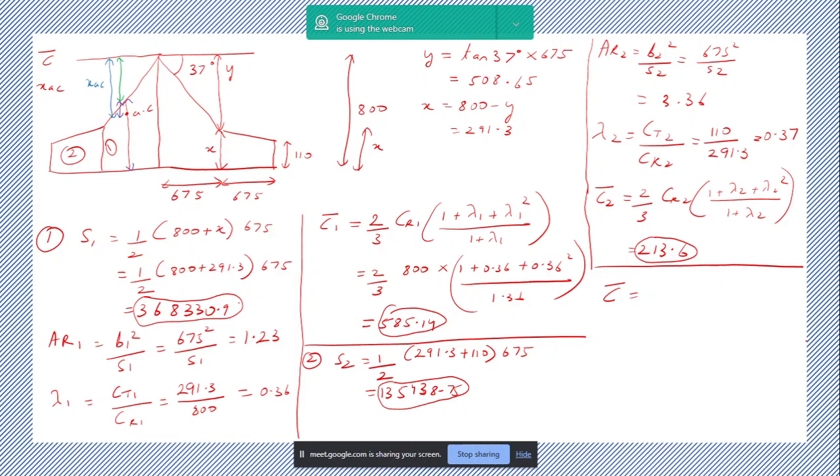It's very analogous to the center of mass. For the centroid, what properties do two-dimensional bodies have? We can't just do c bar 1 plus c bar 2 by 2, because this body can be any shape, right? So what defines its shape? What property will change with the change of shape? Area, yes. So it is c1 bar into s1 plus c2 bar into s2 by s1 plus s2.